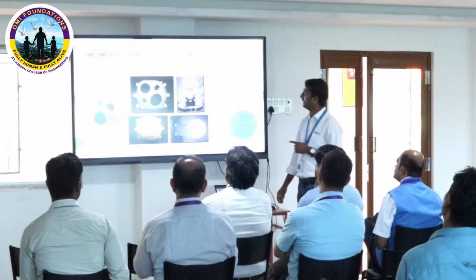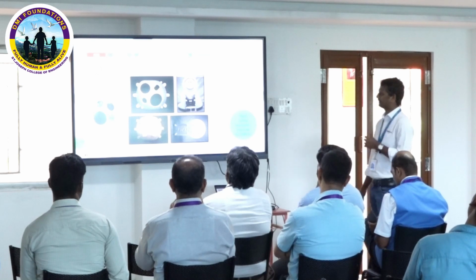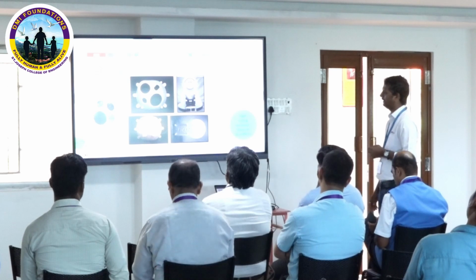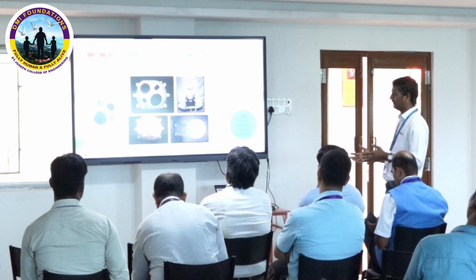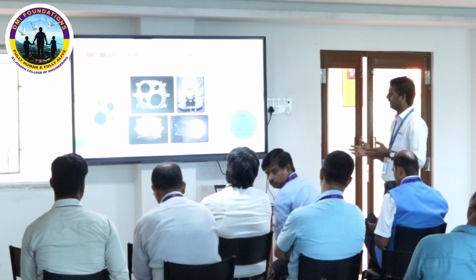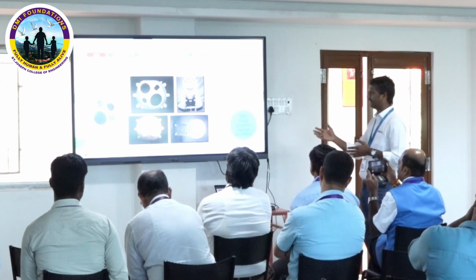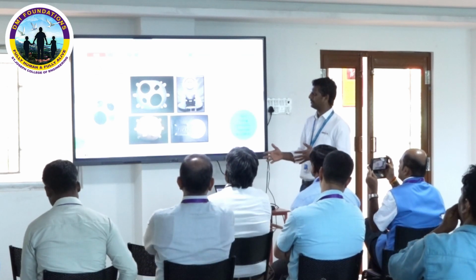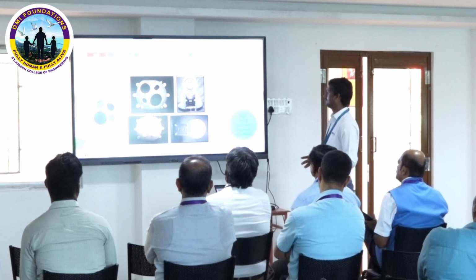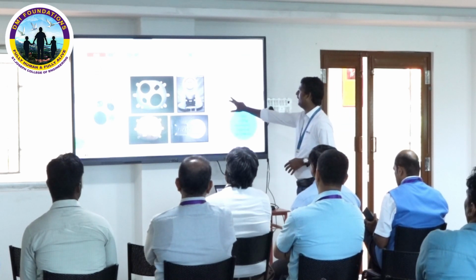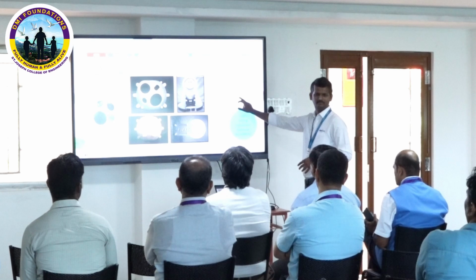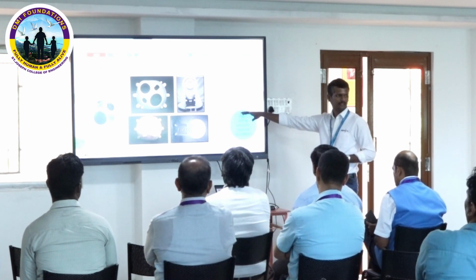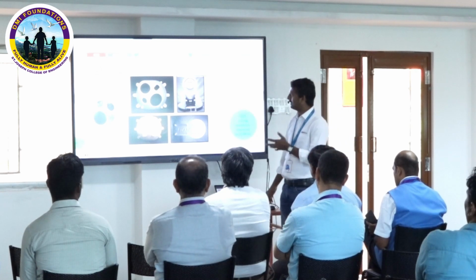In a different sector, we have this gimbal mounted camera housing component, and this component is printed in the M400 machine. The size you can consider is around 370 cross 356 mm. Such a big component is printed in this machine. The lead time for this part is only 30 days. Very less. Usually it will take around 6 months to 1 year in a regular production kind of thing. But here it is not that case.